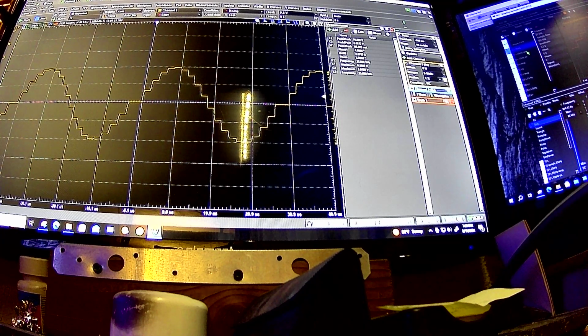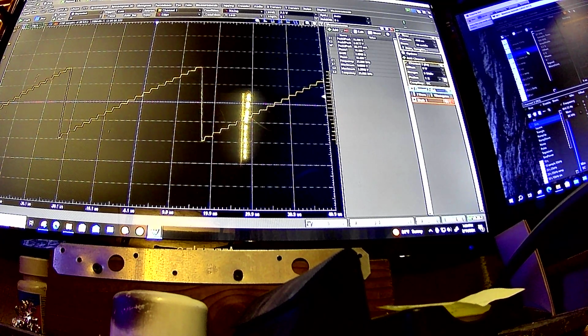But I did a few different waveforms at this same sample rate. So this is what a stepped waveform would look like at this rate. And again, the slew rate at this frequency is still abundantly evident. But that's about as smooth as it gets. It's a definite stair-step waveform, still being roughly 20 volts peak to peak. But let's see, I think I did, no, I think this is the last 20 sample one I did.